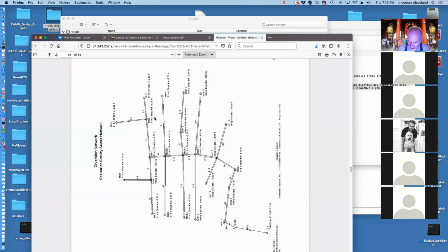A node, a link, or a pump? Waiting for someone to say node. Each of the parallel lines is representing a conduit. When we get to this end, we have a storage unit, goes into a pump, and the pump discharges through a force main to an outfall. So this is totally interfaced to a SWMM model.